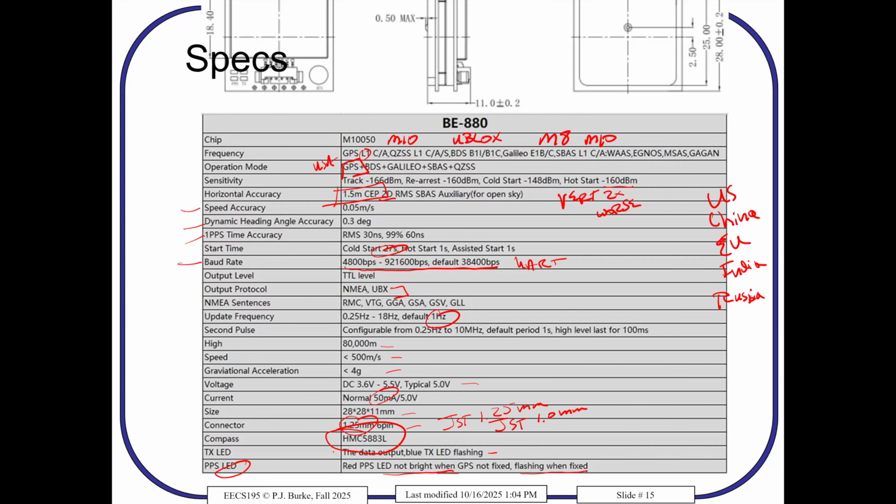If I spin up 2 propellers, I'm going to go east, west, north, or south, depending on which 2 propellers I spin up. But if I don't have any idea what the orientation of my drone is relative to north-south, then I don't know how to move north-south. So the drone needs to have information about the direction it's pointing. And for that, we use the Earth's magnetic field and a compass.